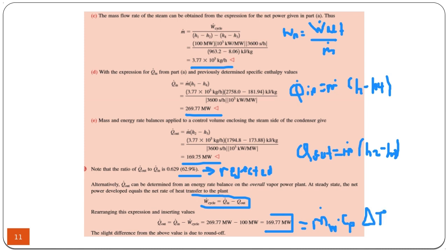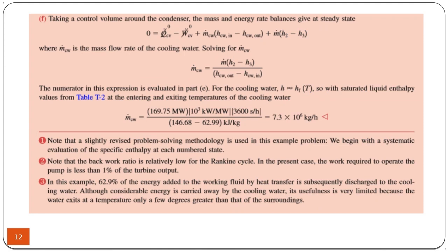Because it's a heat exchanger, as I said, the heat transferred from one side must be equal to the heat received from the other side. So by doing this calculation, this is the thermal balance of this heat exchanger, the condenser. In the condenser, we have a steady state situation where the time rate of change of energy is 0 because it's steady state.